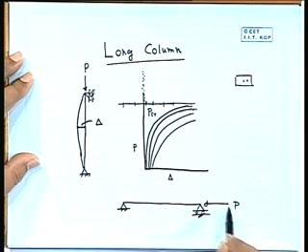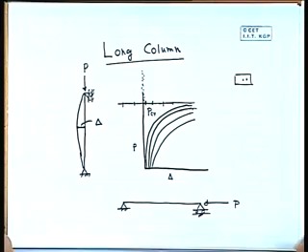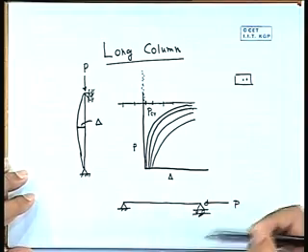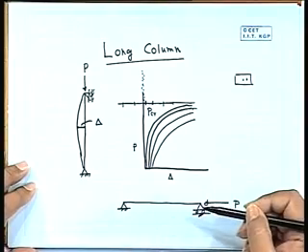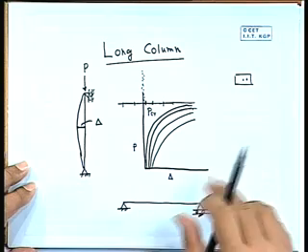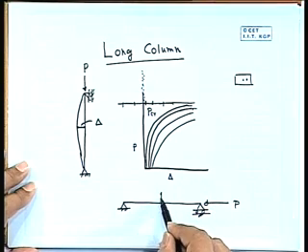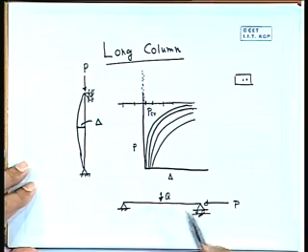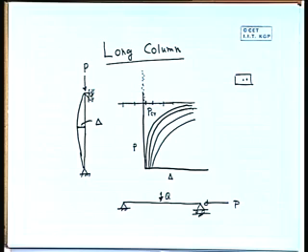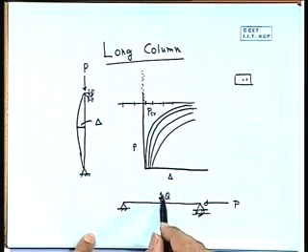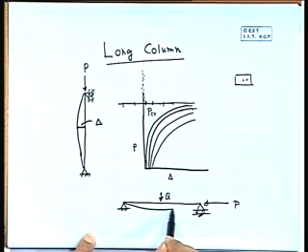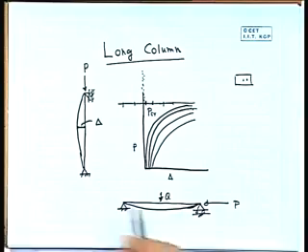See, if we apply some load, it will be under some compressive force P. Now the force can be applied with some eccentricity, so automatically a moment will be there, or we can put some lateral load. Now here, due to Q, we will get some deflection, right.